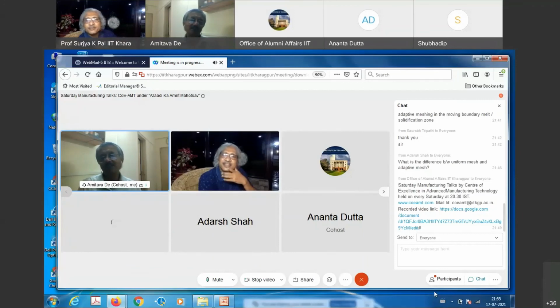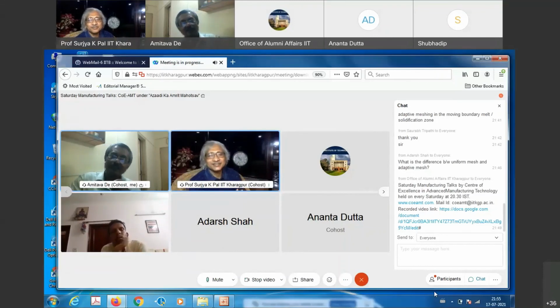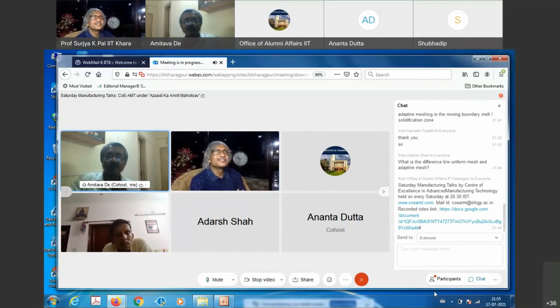Yeah, you're absolutely right. To answer your question in a single thread, whenever we are trying to think of the utility of additive manufacturing, the first important aspect is material. What material are you talking of? Unless it is a low carbon steel, I don't think it is easy for additive manufacturing to sustain. If it is titanium, if it is nickel, yes.